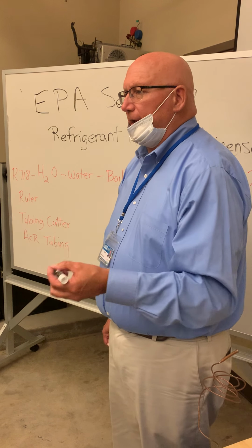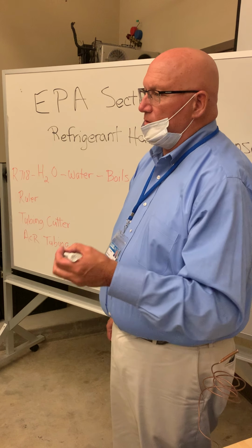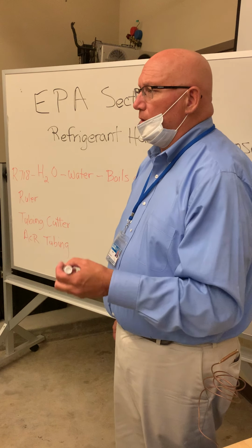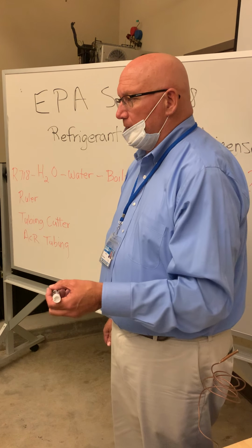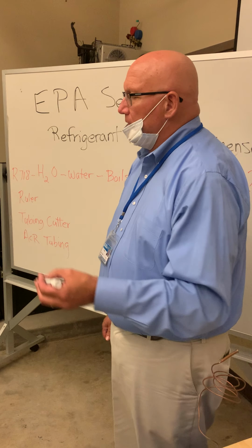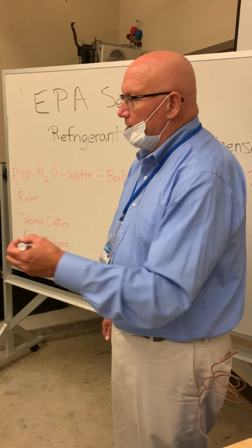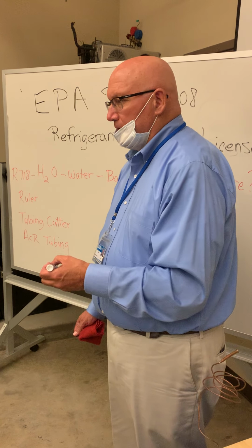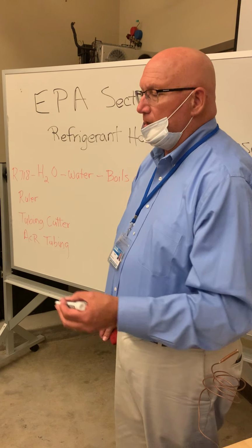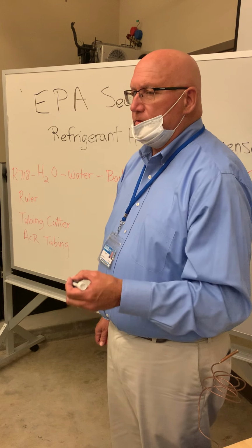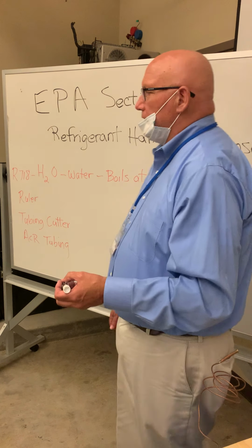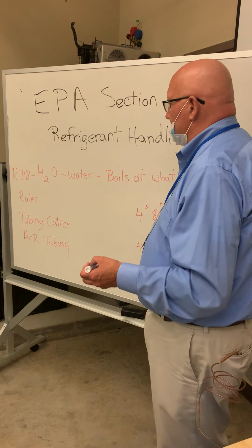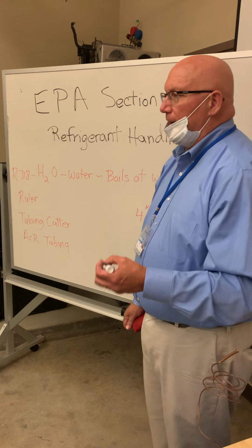This refrigerant handling license, just like that driver's license was foundational, was key, in order for you to work for an HVAC company and to help them charge a unit, recover refrigerant from a unit, store refrigerant, dispose of refrigerant cylinders, anything that involves the handling of refrigerant, you must have the EPA Section 608 license. And that's for handling refrigerant.